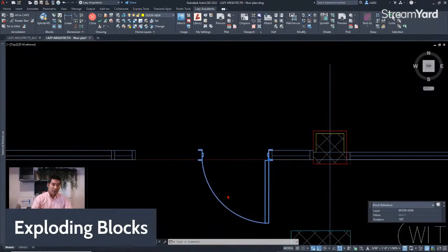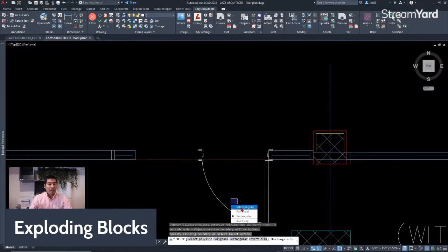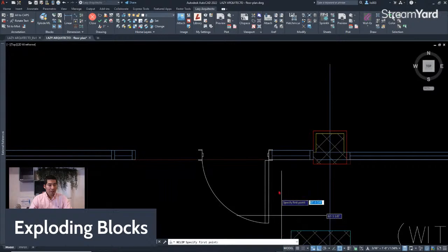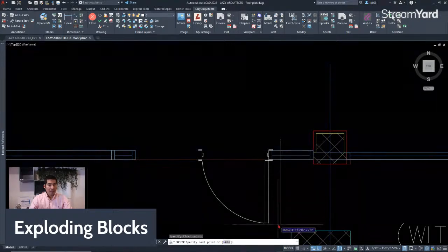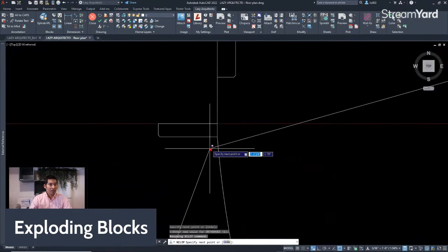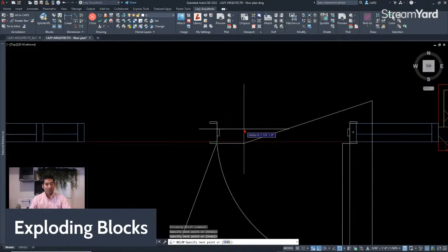So once you do that, xclip, you'll have many options over here. And for this specific example, what we need is the generate new boundary. So click, and then we're gonna pick polygonal, because we're gonna need this option. So once you click that, then we can go and click here, over here, here, and then get closer over here, and then finally I can press enter.